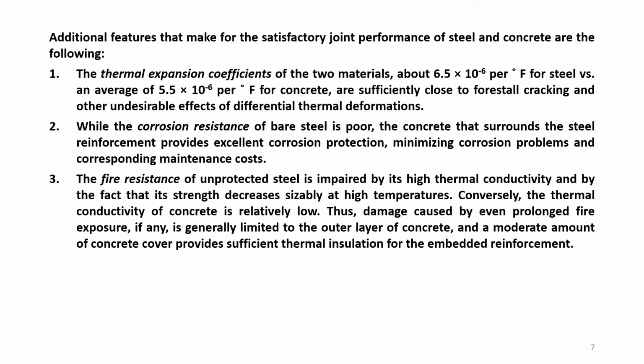That's why a thick layer of concrete will limit the expansion, and then the two materials will remain as one material. They will not separate. If the expansion of one is very close to the expansion of the other, they will not separate and will remain intact. These three are the advantageous points for these two materials to be combined to perform as one material.